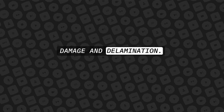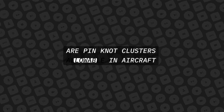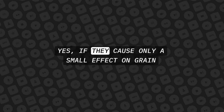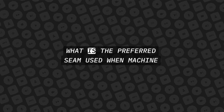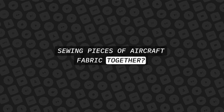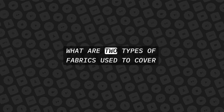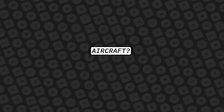Damage and delamination. Are pin knot clusters allowable in aircraft structural wood? Yes, if they cause only a small effect on grain direction. What is the preferred seam used when machine sewing pieces of aircraft fabric together? The French fell seam. What are two types of fabrics used to cover aircraft?